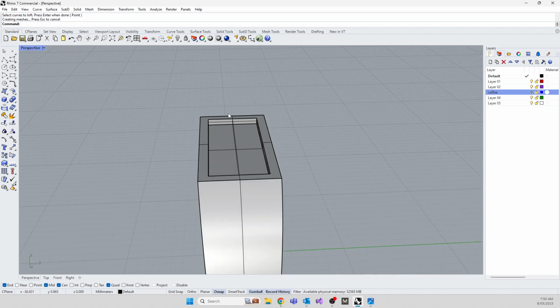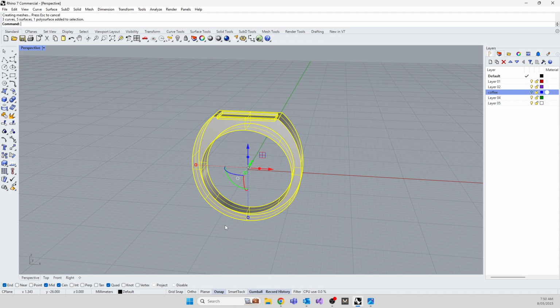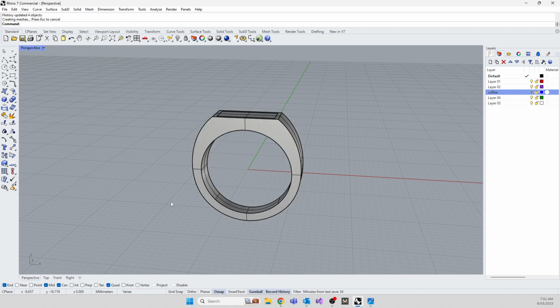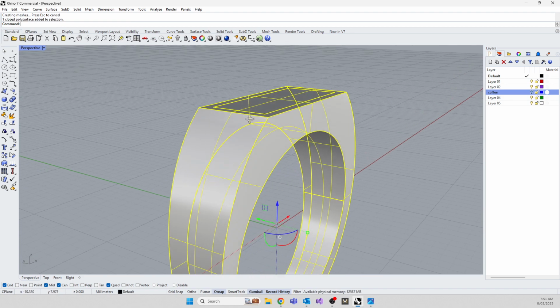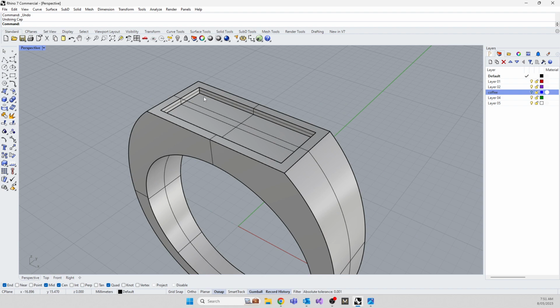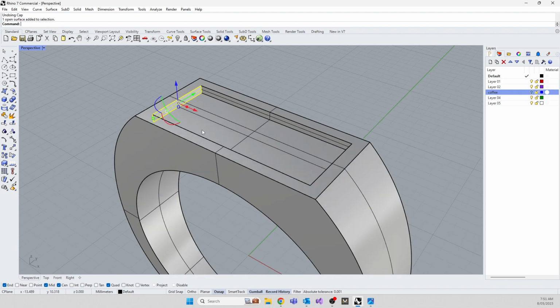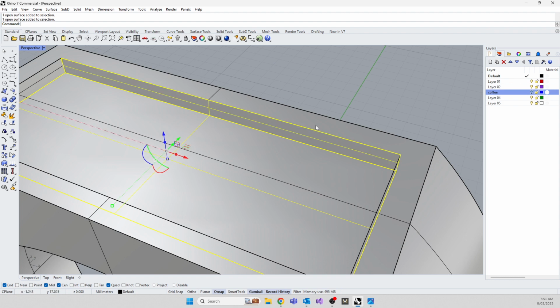I think in the last lesson we learned that loft can't close if the surface is not planar. Last time we had a claw, and we couldn't close one of the claws because it wasn't planar, it wasn't flat. It has to be flat.